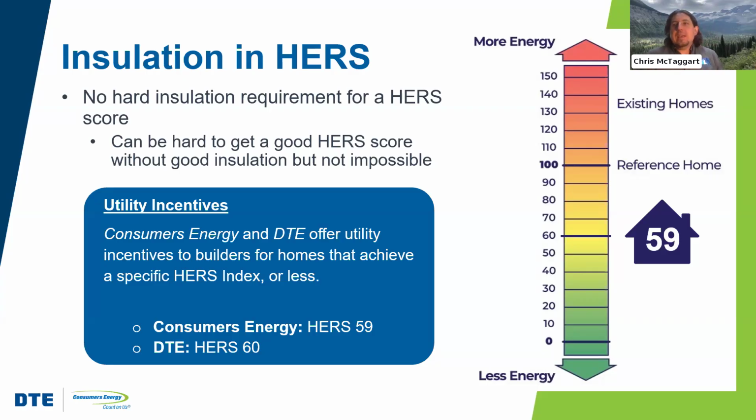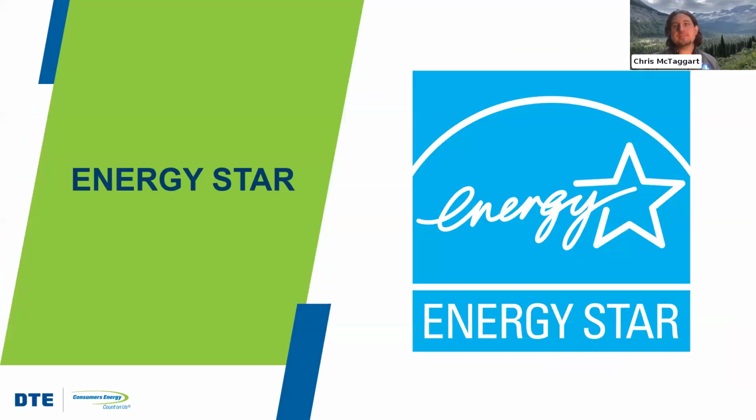Nevertheless, the HERS rating considers not just our insulation levels, but it considers how airtight the home is, how good the ventilation performance is, our heating and cooling and water heating system performance, lighting and appliances. So all of those things are included within the HERS rating. So as a builder, say you want to have better mechanical equipment, but you don't necessarily want to insulate the home in excess, that's an option. You have an option to choose instead to just go for a better HVAC package, but perhaps not the best insulation package. You can still get there with the HERS approach.